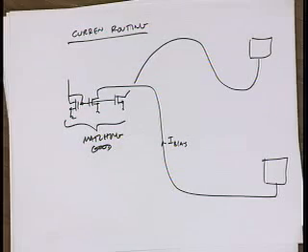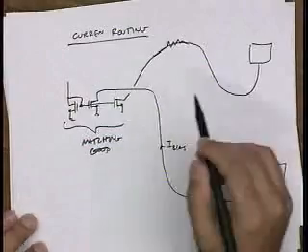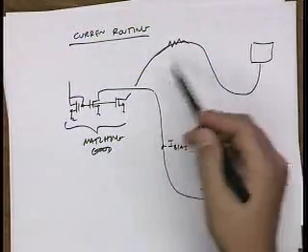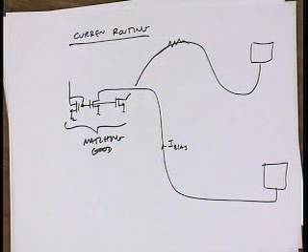Would the IR drop over the wire reduce your swing at the load circuit? Yeah, that's a potential issue. So you basically have resistance here, and that IR drop could start to eat away at your budget. But usually, the current levels we're talking about, milliamps or hundreds of microamps, probably okay. Any other issues with this approach?